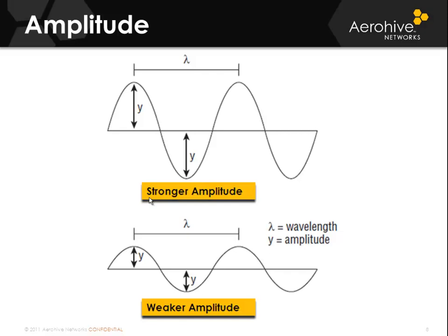For example, if you configure an access point to transmit at 10 milliwatts, that is the transmit amplitude. If you configure it to transmit at 100 milliwatts, that is the transmit amplitude. Antennas are then added to the system, and antennas are bidirectional passive amplifiers. So the antennas will amplify the original transmit amplitude. When a radio receives an RF signal, the received signal is also going to be given some receive amplitude increase due to the antenna's bidirectional passive nature.